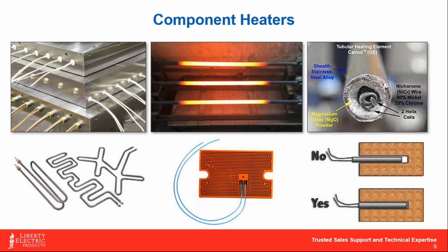And then of course in the bottom right-hand picture, this is just a nice example that depicts you don't want to have an air gap whenever you're inserting a heater into a space. So if we consider our plenum in the upper left, if we have air gaps where those are, I like the design where they came out with the heater on the other tip to know that it made it all the way through with no air gap.